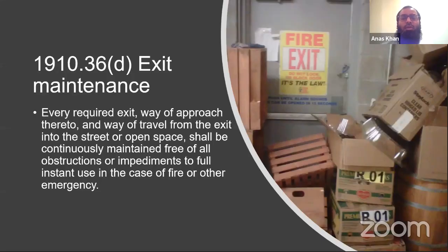Exit maintenance. Every required exit, the approach to it, and the way of travel from the exit into the street or open space shall be continuously maintained. Can you see this picture? Shall be continuously maintained. No stuff, no cartons, no pallets, nothing else. Sometimes you will find plants near the emergency exit, for beautification. Or they think nobody will come to the emergency exit, so this is the right place to keep our cartons and all the old files and stocks, these kinds of things. So these are all not allowed with an emergency exit.